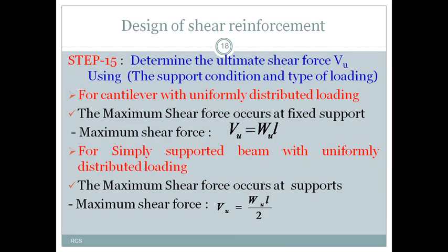So that is the design of shear reinforcement. As we are providing main bars in our beam, those main bars should be tied up with the shear reinforcement, and they should be hung with hanger bars. But here there is no provision of hanger bars. The compression reinforcement will act as a hanger bar. In our singly reinforced beam, there is no reinforcement provided in the compression zone, but we have provided nominal hanger bars to hold the main bars and stirrups in position.